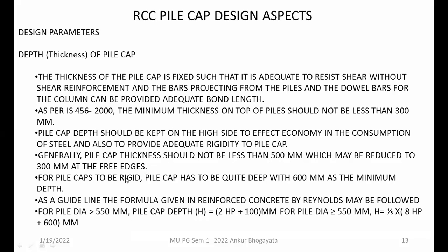So in my opinion, when you are designing a pile cap, please maintain your minimum thickness up to 500 mm. Right. Now, this will not harm the overall behavior, because ultimately it's going to be a block-like element. So there is no fear of bending or flexure. So try to maintain 500 mm as the thickness, and you can maintain a slope, a very fine slope, which